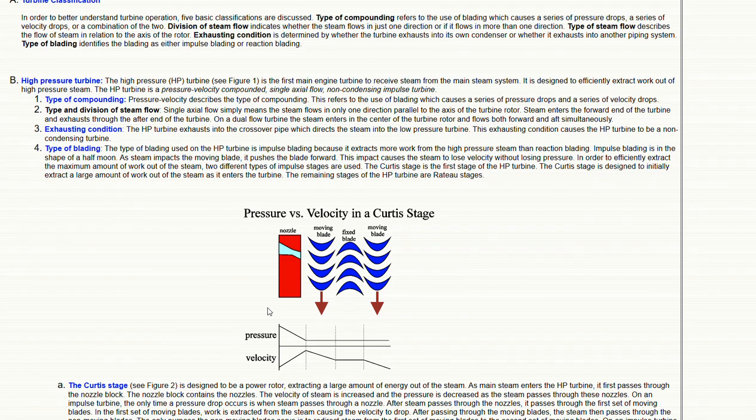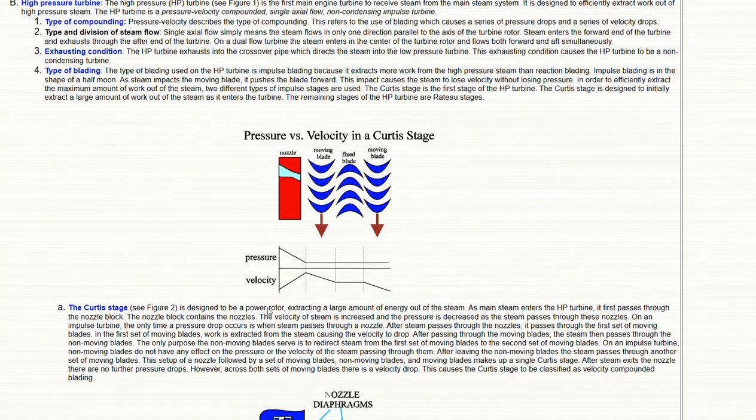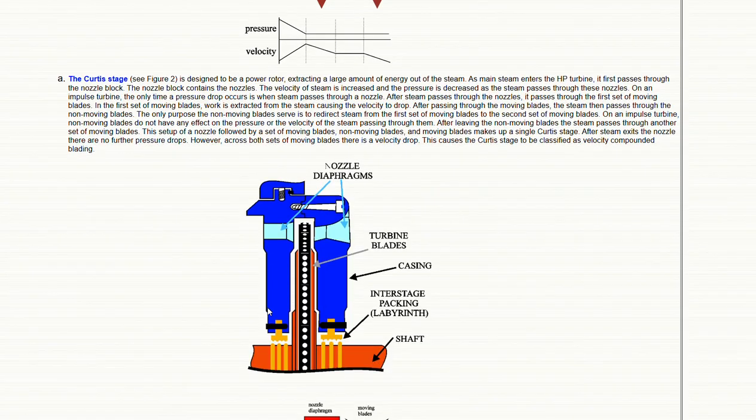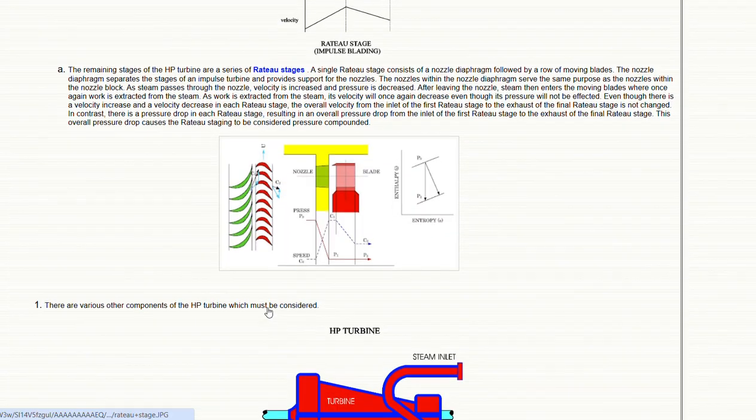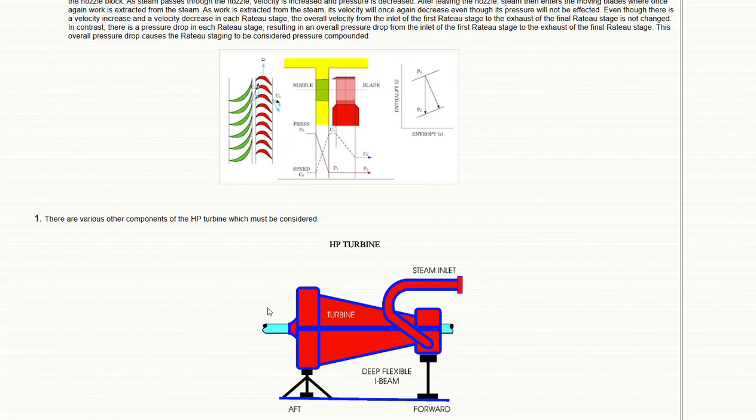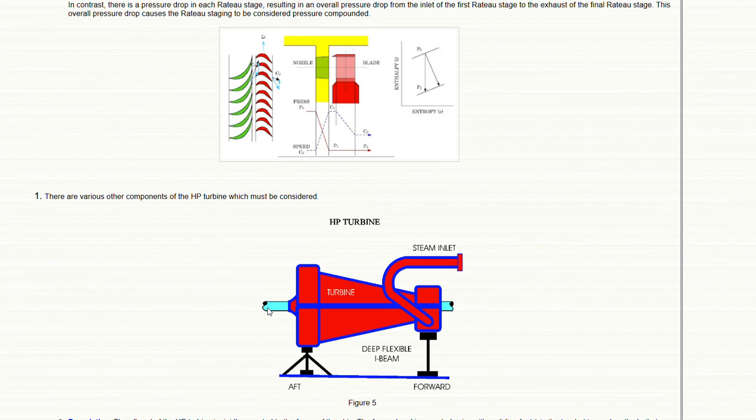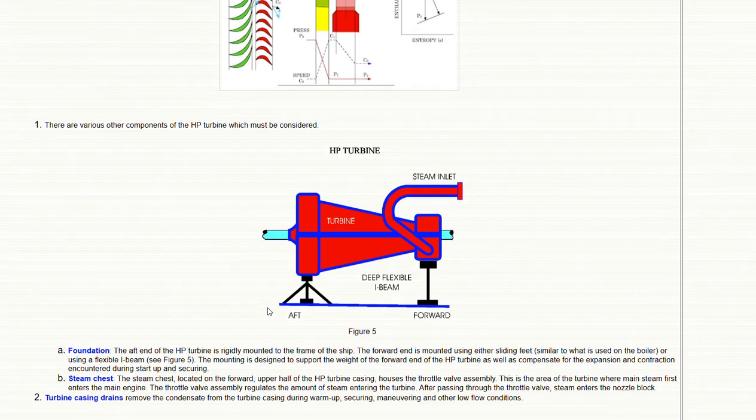While in velocity compounding steam turbines, approximately as a reaction turbine, at every stage we are converting its pressure into kinetic energy. Every stage pressure is dropping and kinetic energy is increasing and then dropping. Okay, and that is the simple concept of pressure compounding and velocity compounding. I have presented it here in a very simple way. You can get ideas of how the turbine section is working.